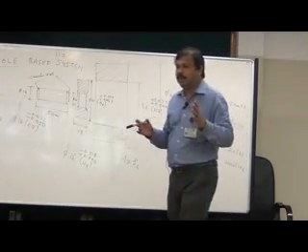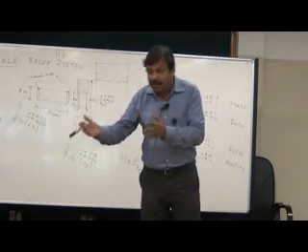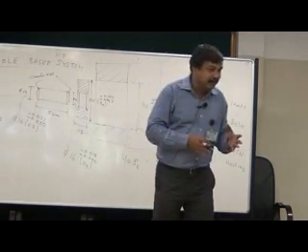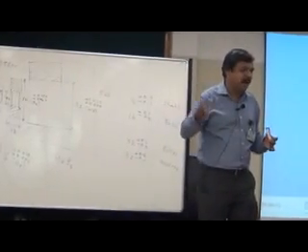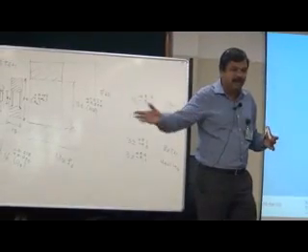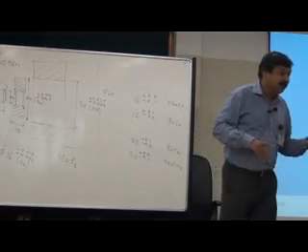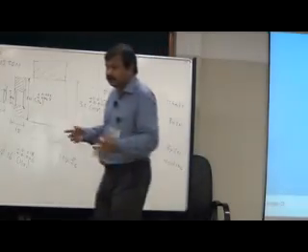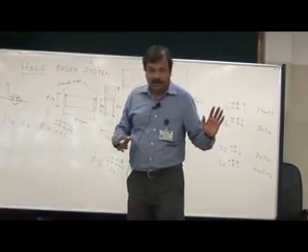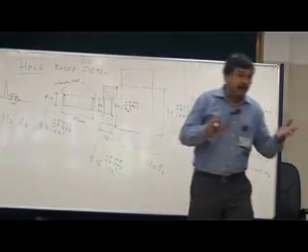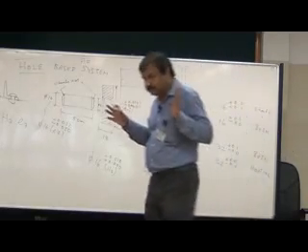And the major problem for Taguchi was that certain bricks are getting overburned and certain bricks are getting underburned. If it is overburned, the appearance will be bad. It may not be very strong. It will be blackish. It has to be rejected. When it is underburned, the ceramic formation would have been incomplete. Again, these parts are to be rejected. Now, what is the problem? The problem is underburning and overburning of bricks.